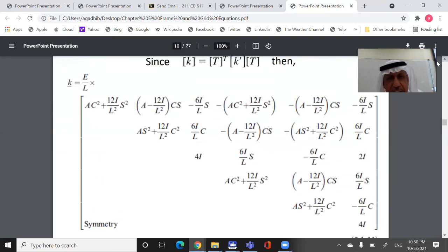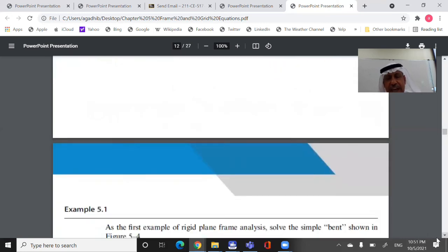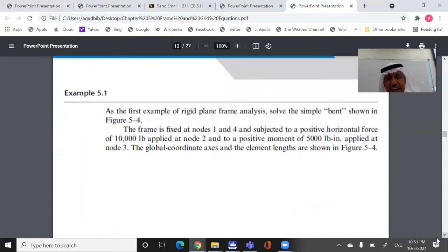Okay. There is S. What does S mean? You took it in truss. What is S? Then it is global. S means sine theta, C cosine theta. It means this is the stiffness matrix for the beam element rotated in any plane, global. Okay, this is global. There is S, there is C. Very good. So from here, you can program this and calculate the stiffness for the 3 elements.